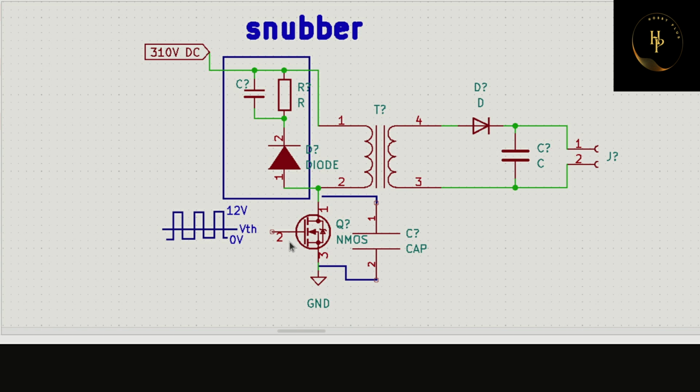But when it is off, then here is a high voltage due to the resonance of the coil and capacitor, a high peak. So the high peak goes through this diode, through this resistance, back to the opposite end and makes it neutral. The primary coil is made neutral. So you don't get any ringing from this point. That is a snubber circuit. That is also a clamping circuit.